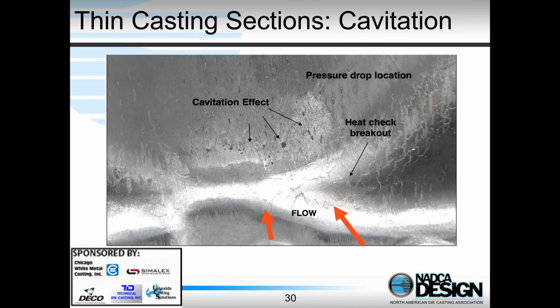And so here's a good illustration. You can kind of see the area marked here, cavitation. This is on the actual die casting. And what happens is that this is just a mirror of what happened on the die casting die. The injection velocity of the liquid metal was so high, we got cavitation bubbles, and these bubbles implode explosively with very, very high forces, and if they do that against the die surface, it's just like shot peening the die surface. And again, we're minimizing die life, and we're going to have to replace this expensive die earlier than we would really like to.